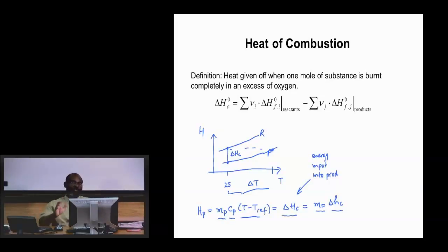The way that we determine the flame temperature for these simple combustion systems is by using a thermodynamic property called the enthalpy. And so we rely on the first law of thermodynamics, and the first law of thermodynamics can be simplified for problems like this to essentially say that the change in enthalpy is equal to the amount of heat that's been liberated in the system.